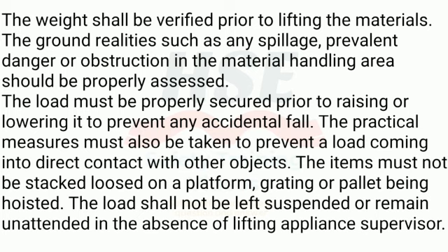The ground realities such as any spillage, prevalent danger or obstruction in the material handling area should be properly assessed. The load must be properly secured prior to raising or lowering it to prevent any accidental fall. The practical measures must also be taken to prevent a load coming into direct contact with other objects. The items must not be stacked loose on a platform, grating or pallet being hoisted. The load shall not be left suspended or remain unattended in the absence of lifting appliance supervisor.